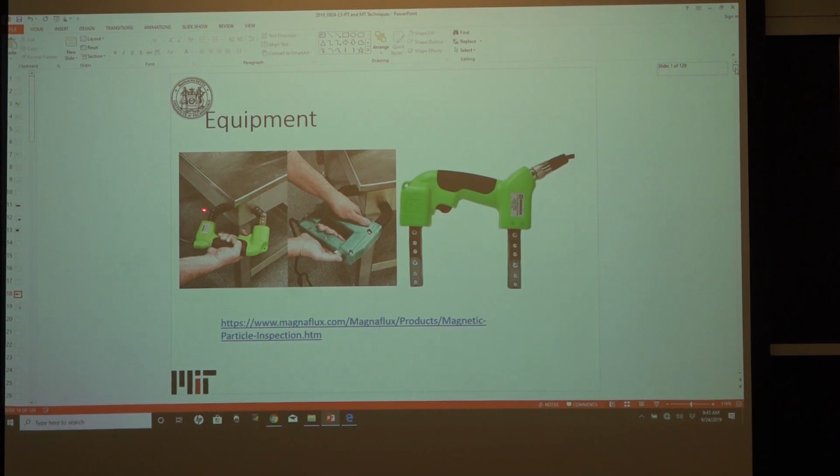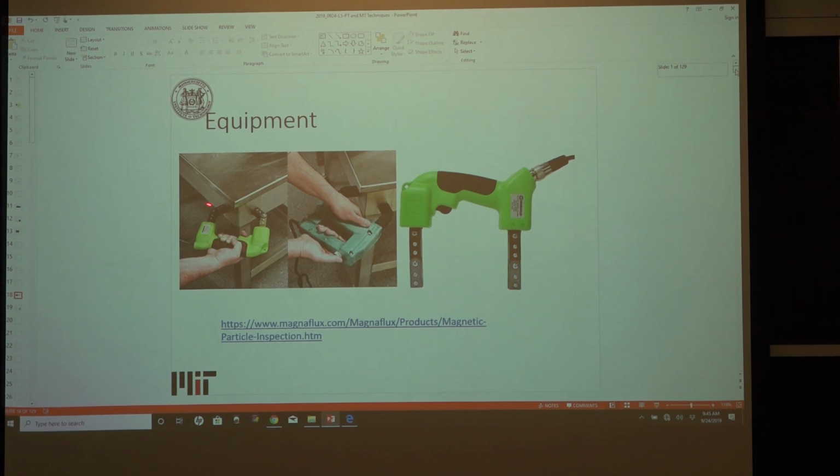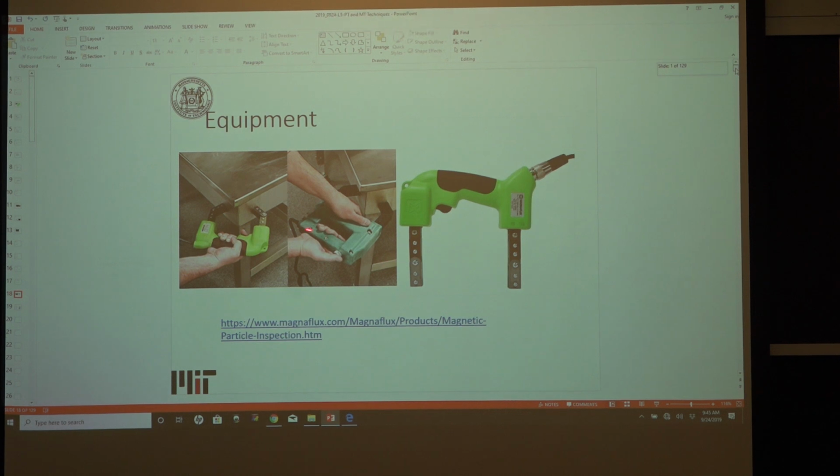The magnetic field only applies in between the areas where the yoke is. So they're actually only looking for flaws right at that edge. And if you look, you can see the fluorescent right there. That's where they're looking for the flaws. Versus if you have a cylindrical tube, you can use a bar magnetization around it, similar to a heat exchanger coil or things like that.